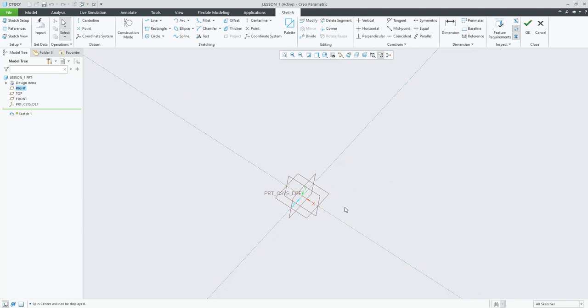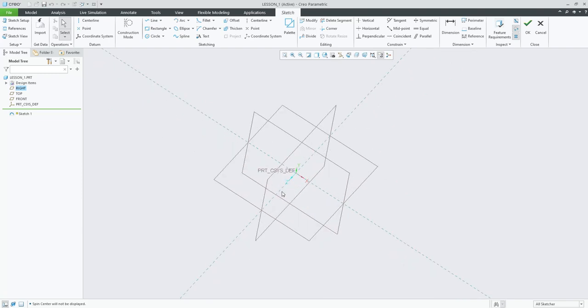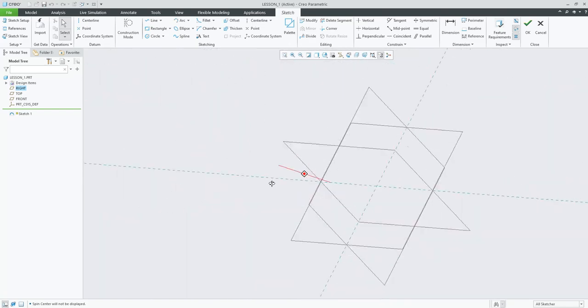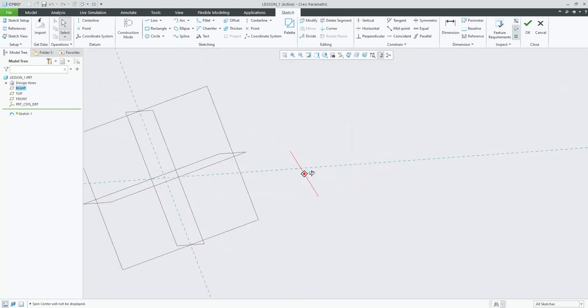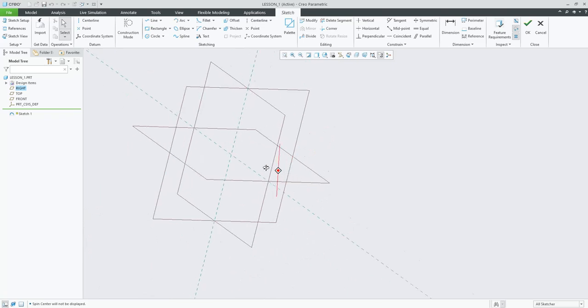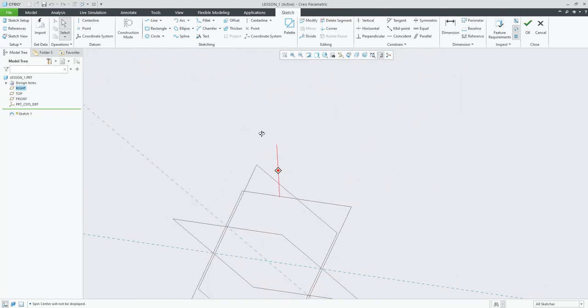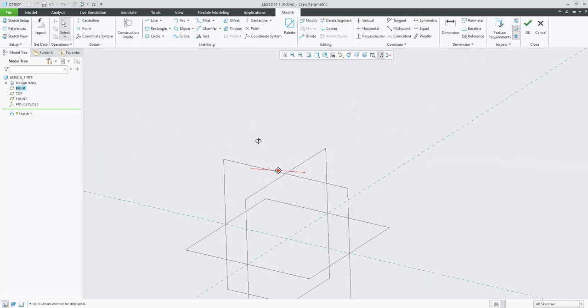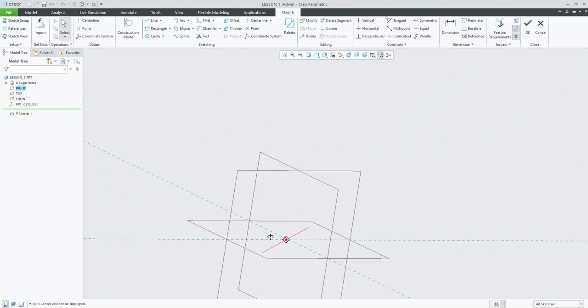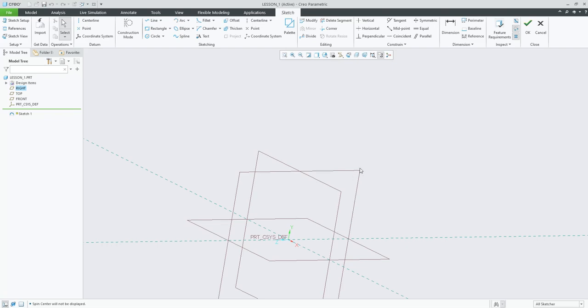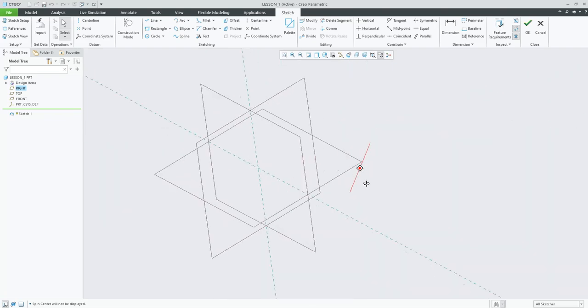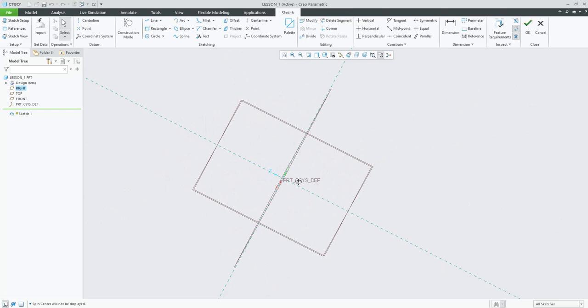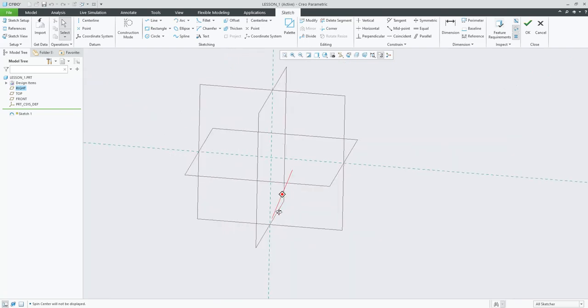So that brings us to rotations and movements. When you want to revolve around something and move around it like this, you hold your center mouse button down and then you move your mouse. And that's what spins the part. You can hold it in the center and rotate it from the center. You can hold it from the corner of this plane, rotate it from the corner of that plane. Anywhere you want, you can rotate it around that point.